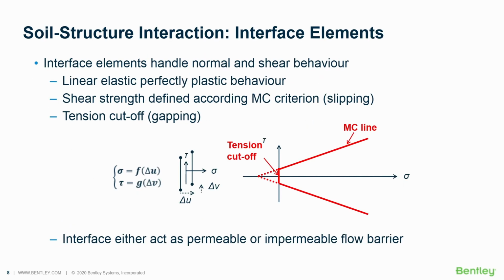Another important aspect related to retaining walls is the soil-structure interaction. Well, I think soil-structure interaction is important in almost any project. This is the reason why Plaxis is becoming so popular. And Plaxis deals with that using interface elements. So the interface element will handle the normal and the shear behavior between the structure and the soil, usually. In fact, those elements are formulated based on the relative displacement on one side of the interface connected to the soil with respect to the other side of the interface connected to the structural element.